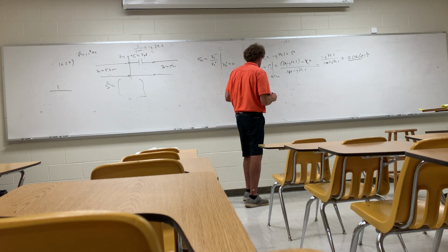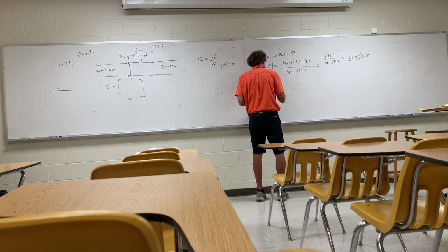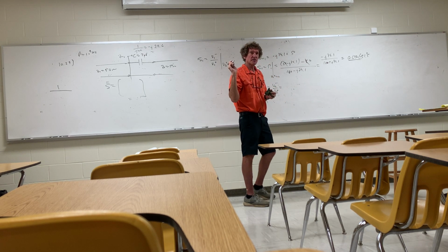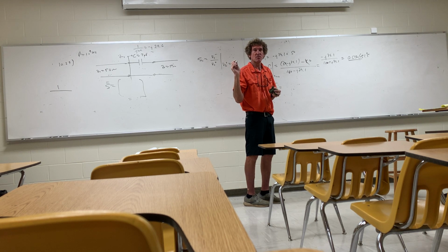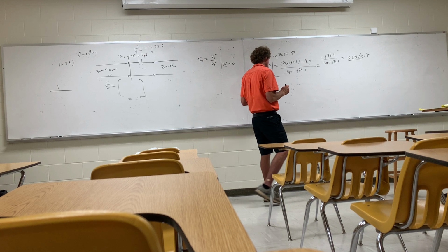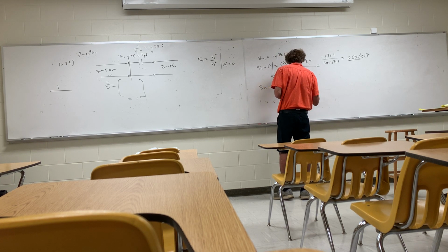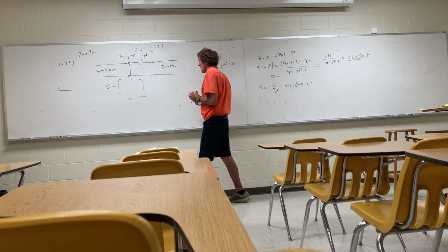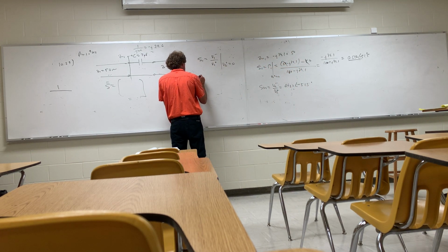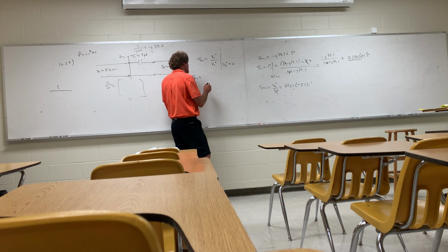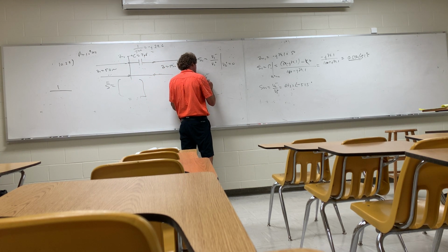Do you want to take a guess at what S22 is? That's V2 minus over V2 plus. What do you think? Same exact thing. Can you look at that and just see how it's reciprocal? It looks the same from either port. There's no topological change in structure. So that would be 0.623 at an angle of minus 51.5 degrees. Now, how do I get S21? Well, what is that? S21 by definition is going to be V2 minus over V1 plus. It's a voltage gain, assuming V2 plus is 0, right?